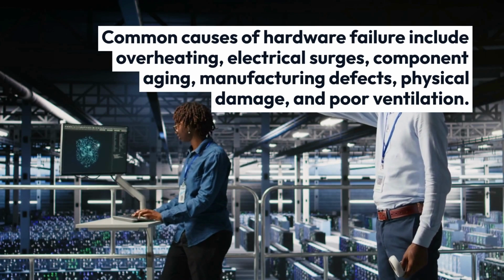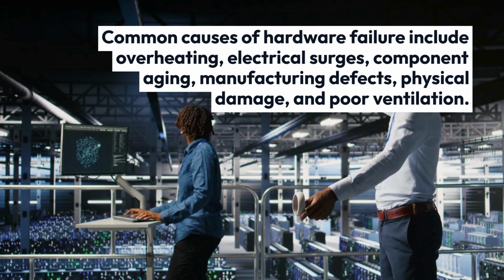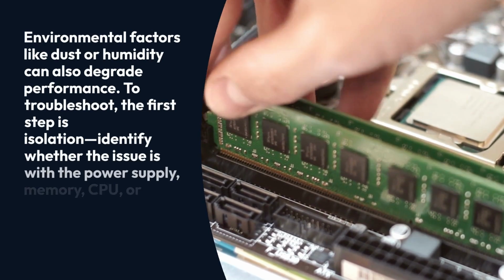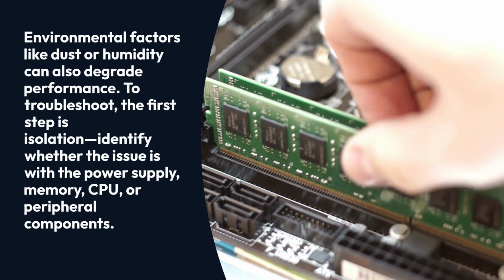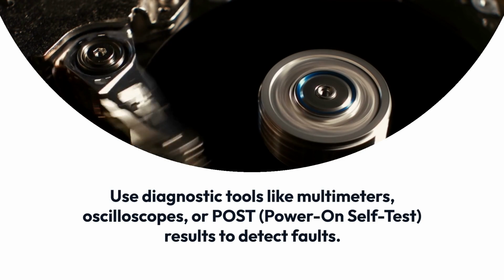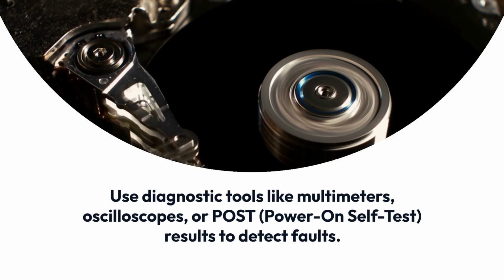Common causes of hardware failure include overheating, electrical surges, component aging, manufacturing defects, physical damage, and poor ventilation. Environmental factors like dust or humidity can also degrade performance. To troubleshoot, the first step is isolation. Identify whether the issue is with the power supply, memory, CPU, or peripheral components. Use diagnostic tools like multimeters, oscilloscopes, or power-on self-test results to detect faults.